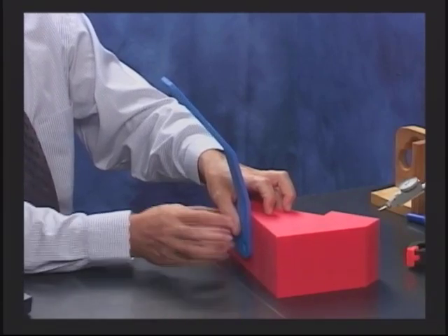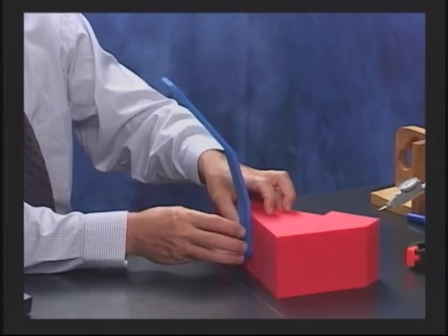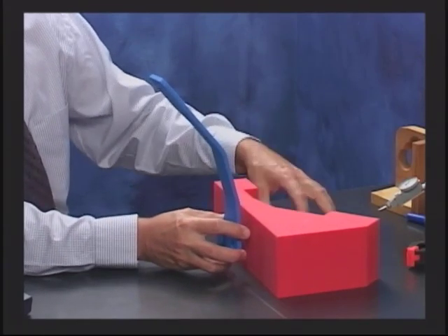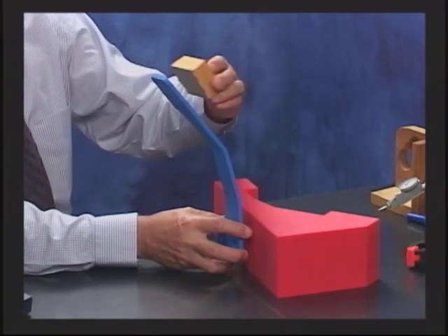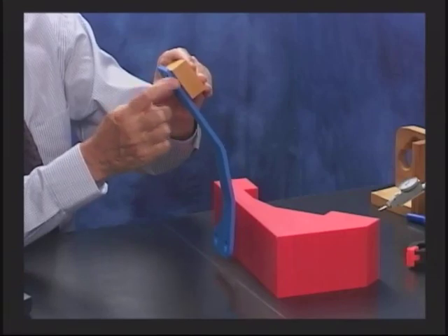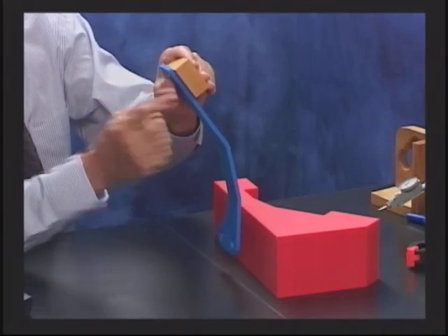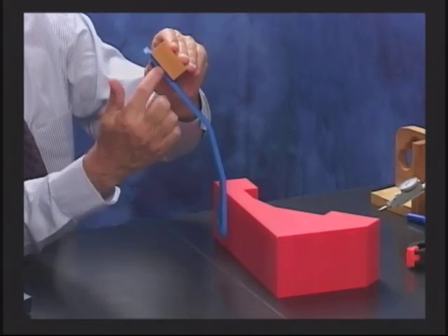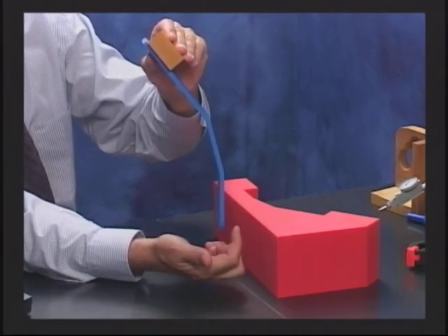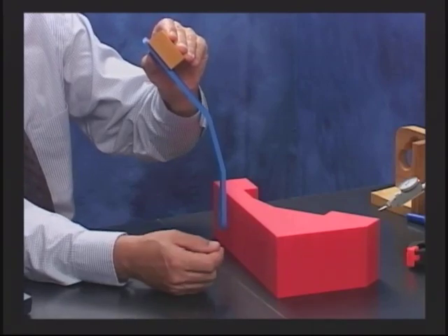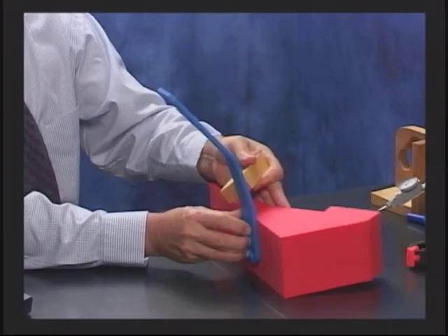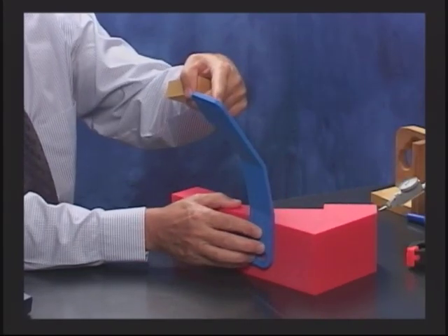Now, sometimes, remember what I told you is that we want to be able to look at how the part mounts, the leaders and the followers. Now, some people say, well, you talked about datums where it mounts. It also mounts on this surface, and it does. But if I was to call this the datum, and I said that was the leader, then since that's the datum, this surface is going to have to come in and have some tolerance to tell me how much it can be off. Well, if I said that this could be off within 1 millimeter or 2 millimeters, it's not going to be off. When it goes on, it goes on. And what happens? This surface is the one that's off.